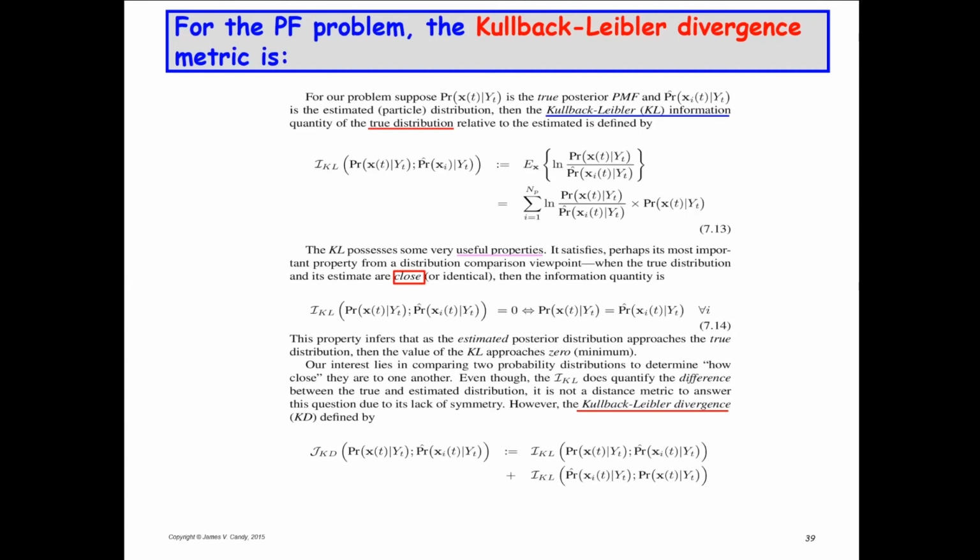I should mention too that the Kalman filter is a Bayesian processor, because we can prove that. But it's sort of backwards in the sense that it's already assumed that the posterior distribution is known, that it's multichannel Gaussian. And so you can think of the Kalman filter as Bayesian, but we already know what the posterior distribution is. It's a multichannel Gaussian distribution. And so the Kalman filter, in my mind, is an efficient way of sequentially or recursively calculating the posterior conditional mean and the posterior conditional variance. So it is a filter, but that's why it's much easier than having to do all of these resamples and use particles to estimate the posterior, because you already know what the posterior is. You've assumed it. And it's unimodal Gaussian. And so anyway, I throw that in since I was there.